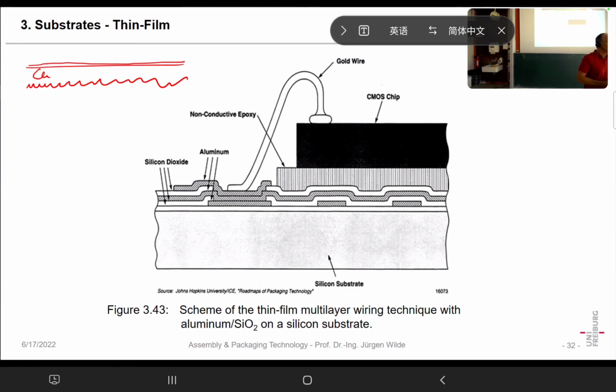Yes, in fact, the material then is not called photoresist, but it's a photoimageable polymer. And the most important photoimageable polymer here is polyimide. So you can modify polyimide in a way that you can make a positive or a negative resist of it.